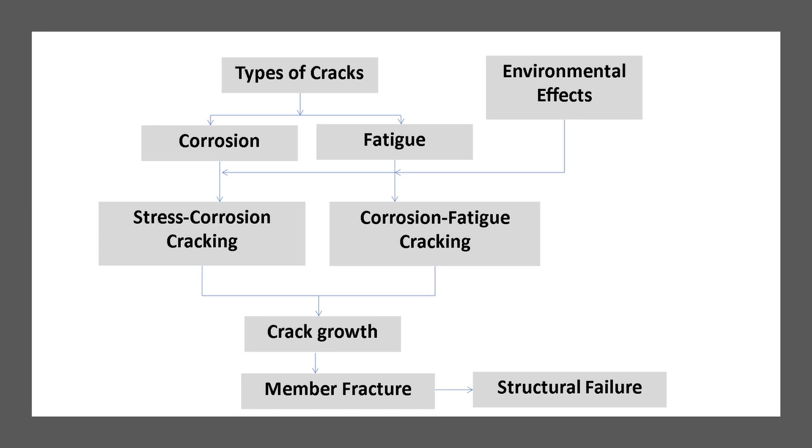Similarly, fatigue cracks will grow further with the assistance of this environment. Eventually, crack growth will extend to a size that cannot be tolerated by the fracture toughness of the material, and brittle fracture will occur under stress levels that may be lower than the design stresses. This may cause structural failure in some cases.